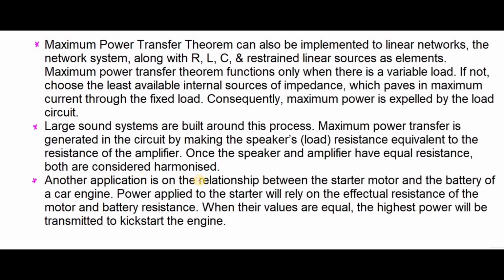It is also used in the application based on the relation between the starter motor and the battery of a car engine. Power applied to the starter will rely on the resistance of the motor and the battery resistance. When their values are equal, the highest power will be transmitted to kickstart the engine.